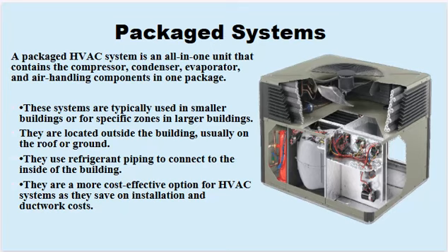Compressor. The compressor is the heart of the HVAC system. It compresses refrigerant gas, raising its pressure and temperature, and sends it to the condenser. Condenser. The condenser cools the high-pressure refrigerant, causing it to condense from a gas to a liquid. This liquid refrigerant is then sent to the evaporator coil to absorb heat from the indoor air.